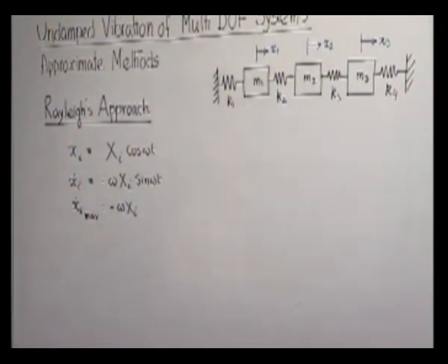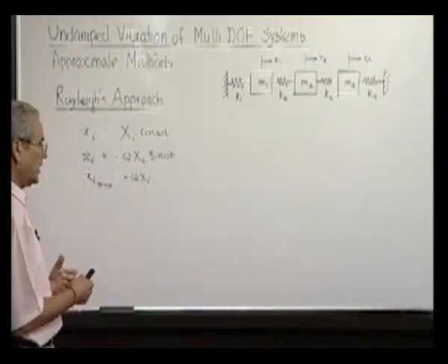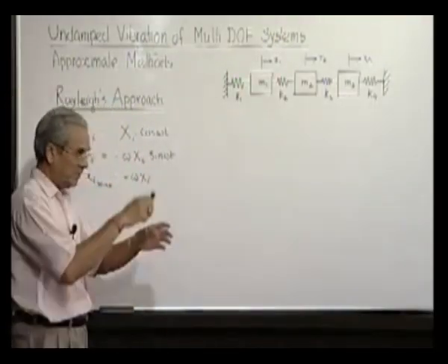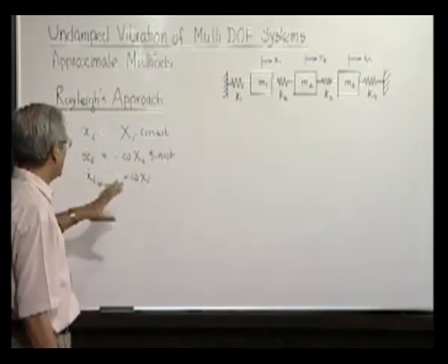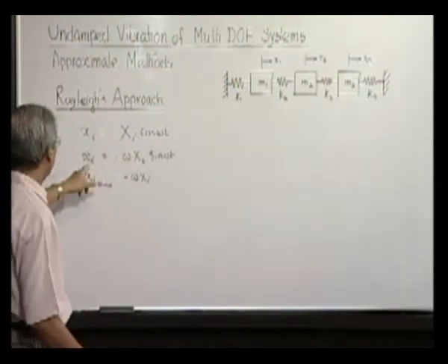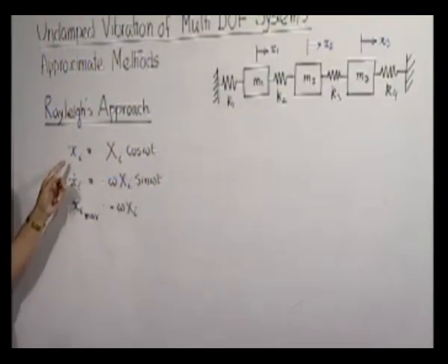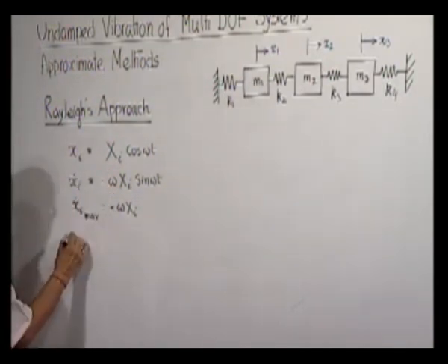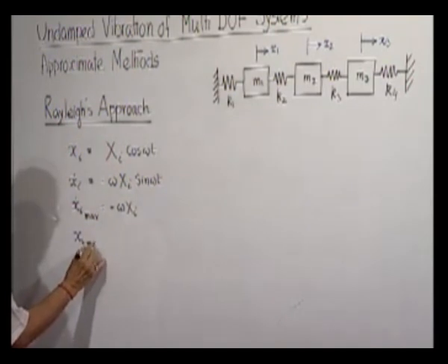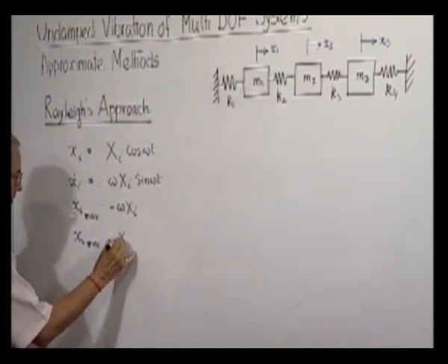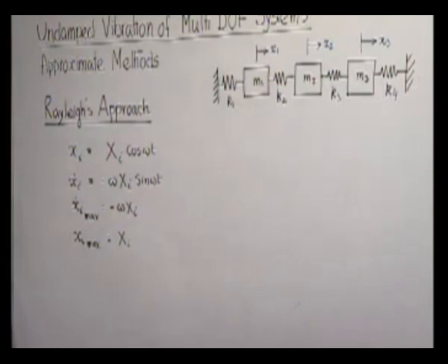Similarly, all these masses attain their extreme position, which represents the extreme stretching of all the elastic members, or if there is gravity, then the extreme position in the gravitational potential energy well. So, we know that extreme positions are all attained at the same instant, and the values are nothing but the capital Xi. So that is also quite straightforward, because the maximum value of cosine omega t is 1.